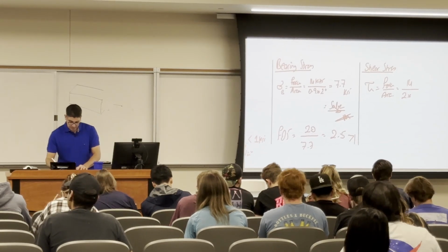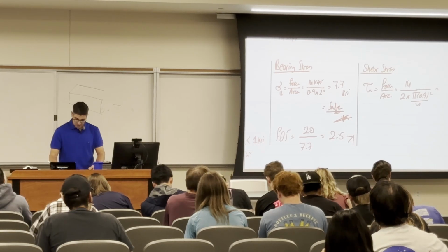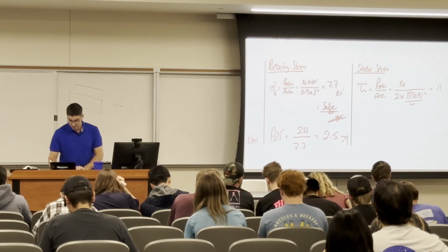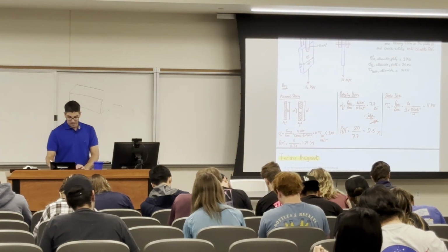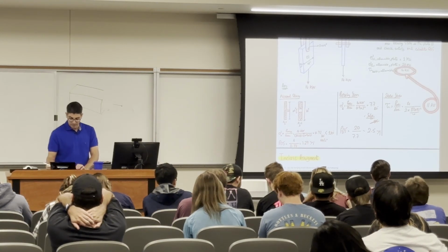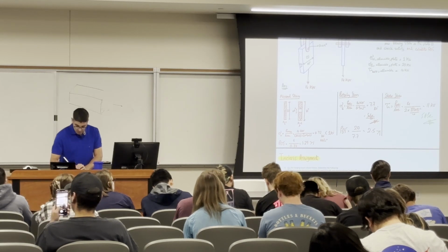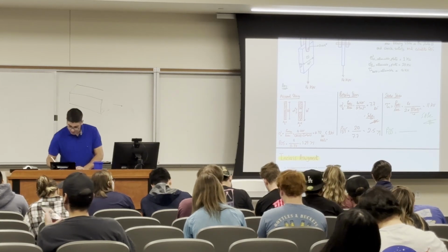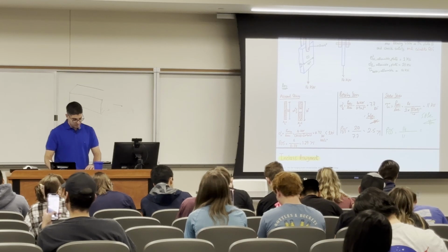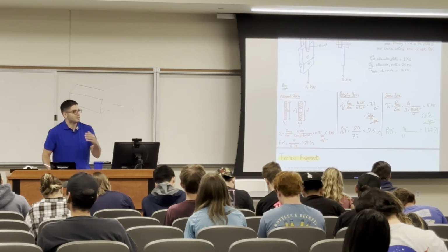Okay, so 2 times what? Pi d squared over 4. What is the area? What is the stress? I got 11 KSI. Okay? 11. And what's the allowable? 14. Am I safe or unsafe? Safe. So you can write safe in green and make your signature, and then FOS. Capacity. What's my capacity here? 14. What's my demand? 11. So I'm safe by 1.27. As long as it's greater than 1, I'm happy and you are happy, right?